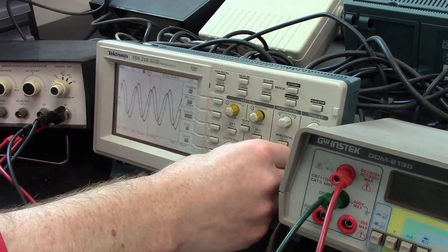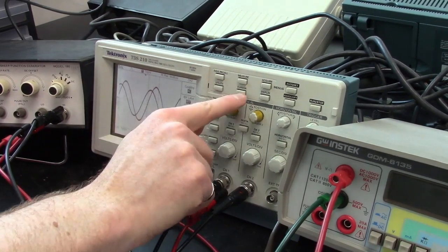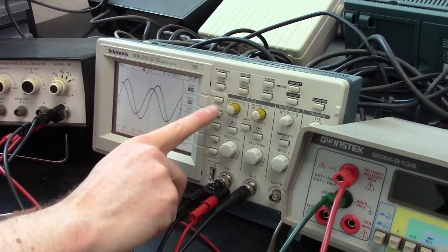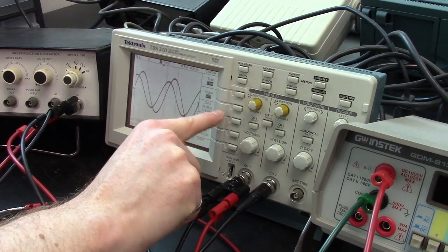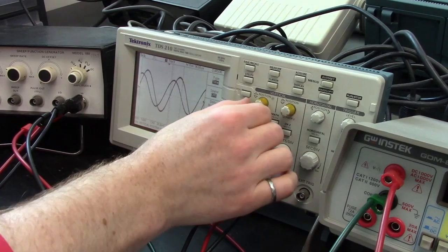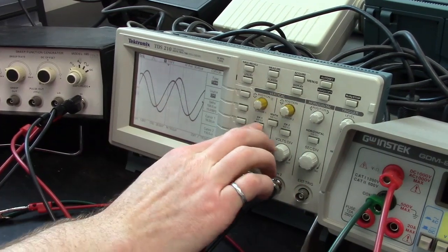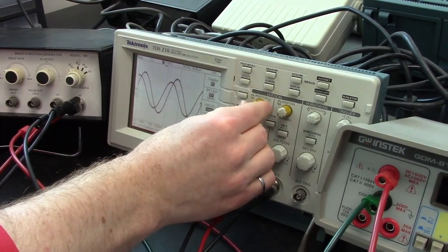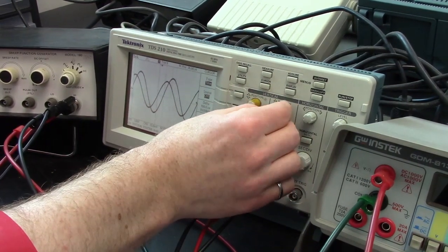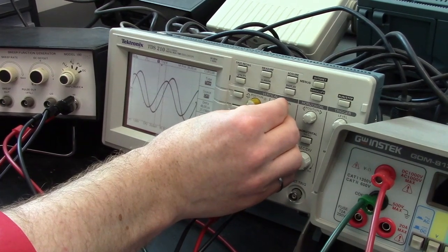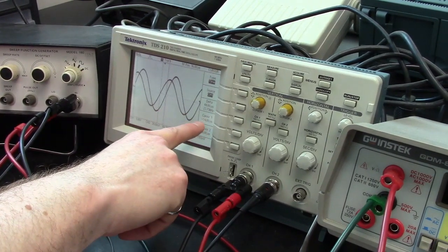So to figure out exactly how much this is delayed, we can increase the time scale here and then use cursors. So what we'll do is we'll hit the cursor menu here, and you can change it between off with the type button and voltage and time. We need time cursors for this. And now once you're on the cursor menu, these two knobs here at the top, rather than adjusting the voltage up and down, will now adjust the two cursor positions left and right or up and down. So a good way to take this measurement is to look for where the signals cross the axis, and then it will tell you the difference between the two cursors.